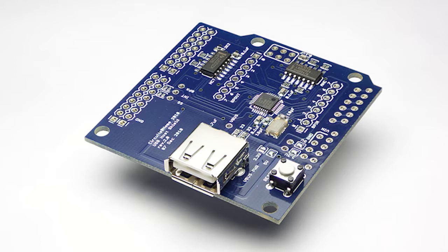Now when different peripherals require different clocks, it doesn't make sense to add different crystals for each of them. That is why all the clocks inside are connected to the main system clock, which can be configured using registers to generate any clock that you want. We'll come across that in the startup code when we'll be doing that. So that is the main system clock, right?